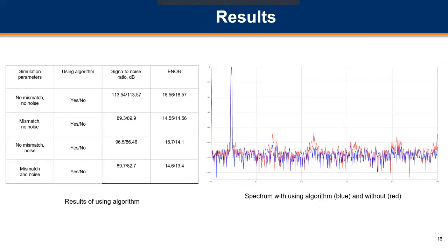The table shows the result of the model's operation when digitizing 1,000 samples. The difference between the schematic model with ideal elements and the mathematical model is about 10 to the minus 9 power volts. And the speed of the mathematical model is 10 to 12 times larger than the schematic model. The array consists of 3 sections with 6 capacitors in each one.